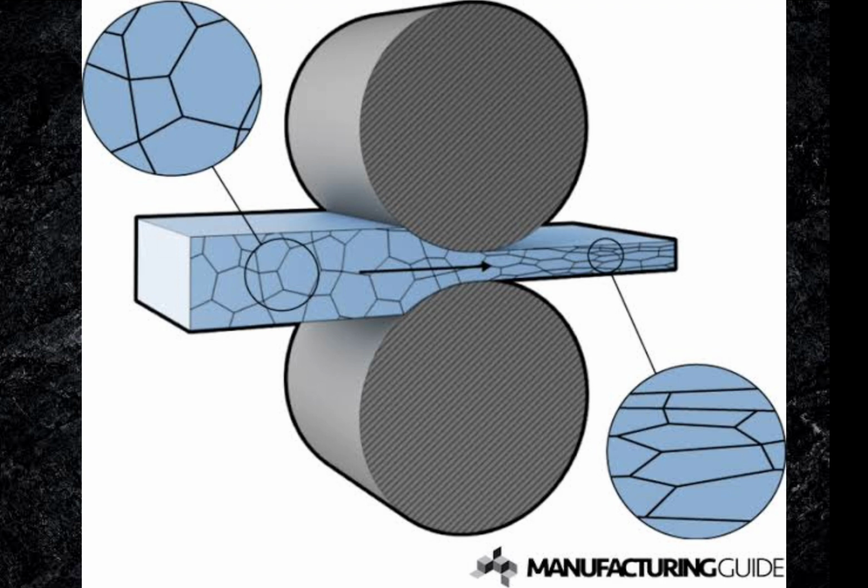Three ways to identify cold-rolled steel are oily or greasy, a very smooth surface, and very sharp edges on a bar stock. Cold-rolled steel is commonly used for machine parts, automotive components, and much more.